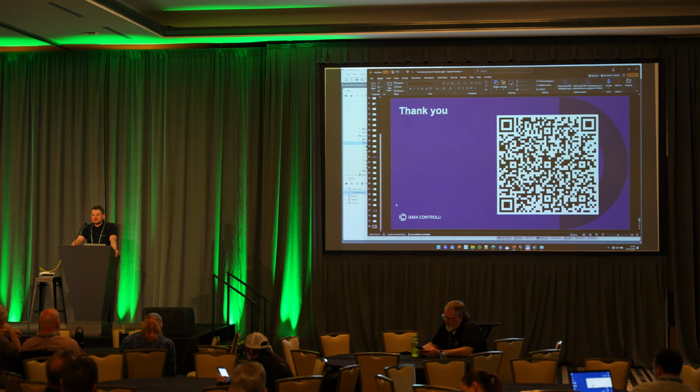You can override it over the network. So you can configure that directly on the dip switches, but there's a way to just override it over the BACnet network whenever you need to. That's what I was curious about. Thanks.